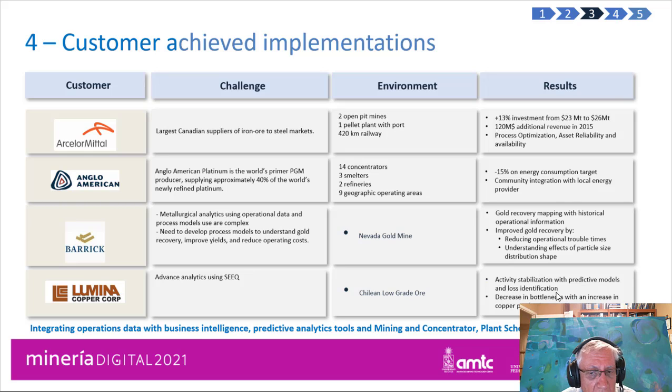And that is really how people change, when you are following the money on how you're operating the plant. So we are decreasing the bottlenecks, and this is very important to identify where the constraints are and how the bottlenecks are changing depending on the type of ore that you are producing. Because the rheology changes according to the size distribution, mineral type, and so on. So it's a never ending story there.